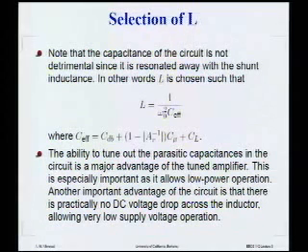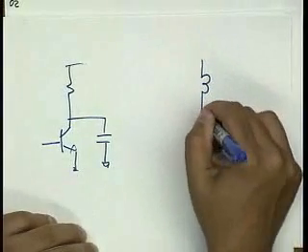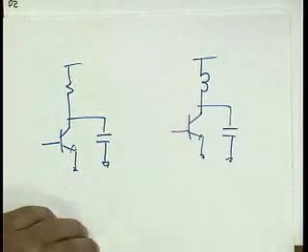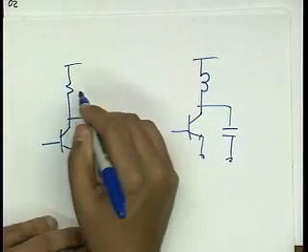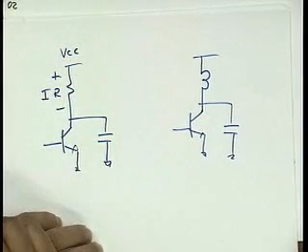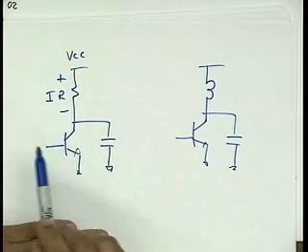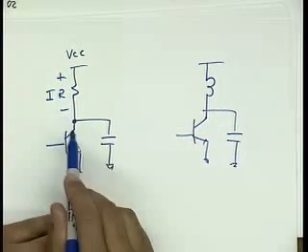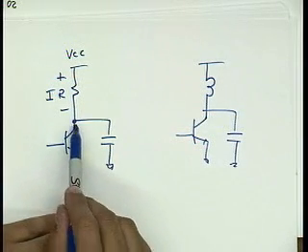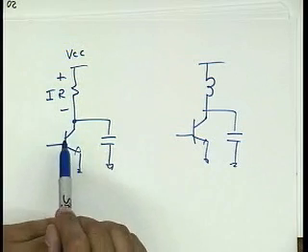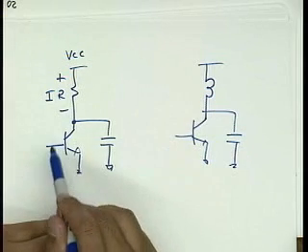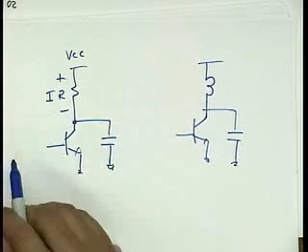It's amplifier 1 and amplifier 2. In this amplifier, this is VCC, I have an IR drop across this resistor, which is eating into the headroom. In other words, I have to make sure this output voltage doesn't get too low, because if it gets too low, I basically put this device into saturation, excuse the terminology, and then this transistor is no longer forward active and it can't provide gain.